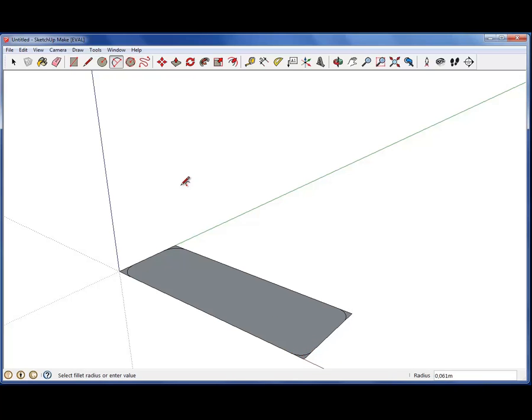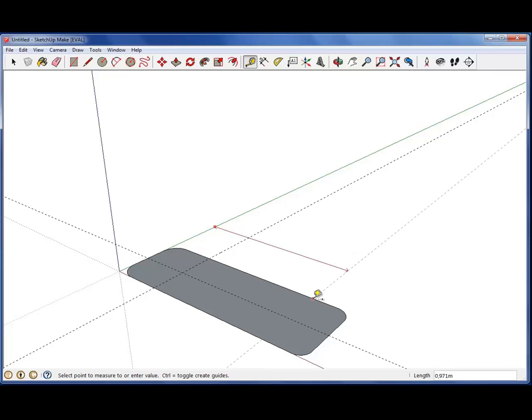Now I am drawing a rectangle, then use a special tool to smooth the corners. It's not the exact procedure. I clipped some intermediate steps to make the video more dynamic. You can draw some objects. SketchUp is the exact name, because it is like drawing on a piece of paper with a pencil. I'm making guidelines, and then I can draw some holes in this plate of metal.